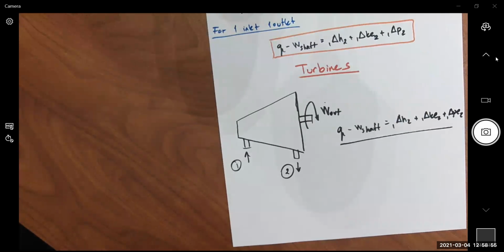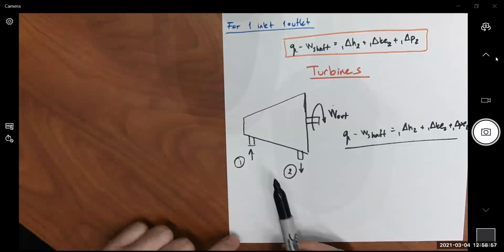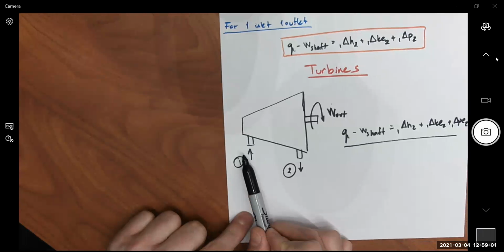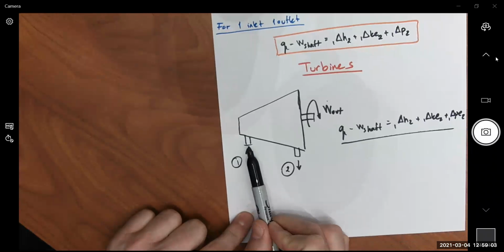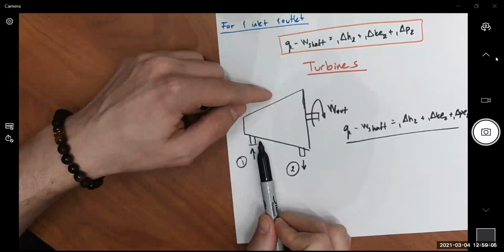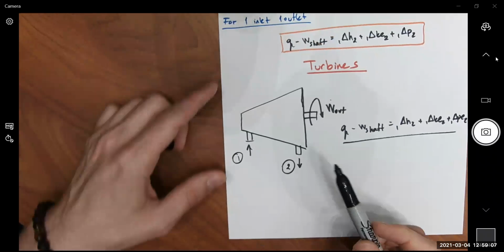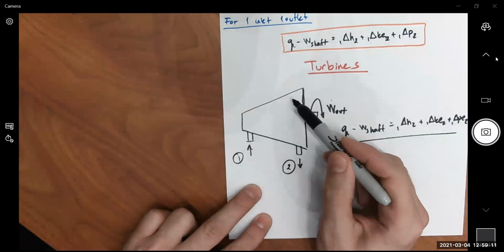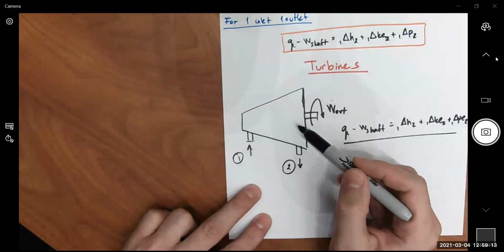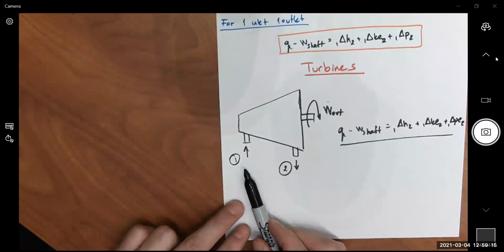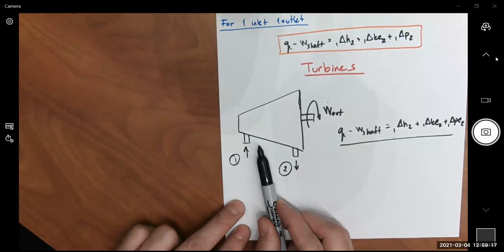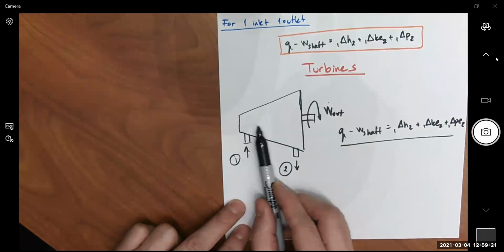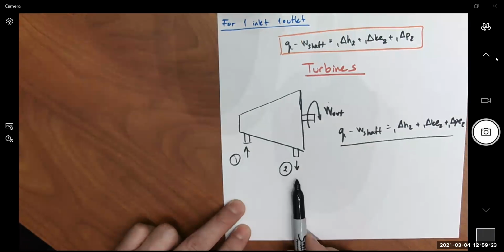What a turbine does is we have a high energy content substance entering the turbine. What a turbine does is expand the fluid. Right? It has blades inside, hundreds of them. That high energy content fluid hits those blades, turns those blades, produces work, and you take the lower energy content fluid out.